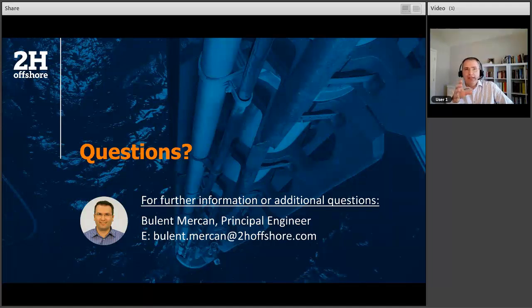But again, it highly depends on what data you are collecting, how many channels you are using, how many sensors you have, and also what your logging configuration is. Are you collecting data continuously, or, like I said, say 15 minutes or 30 minutes every 2 hours or 3 hours? Then you will have longer battery life. It is also acceptable if you do such intervals, especially for long-term fatigue assessment.